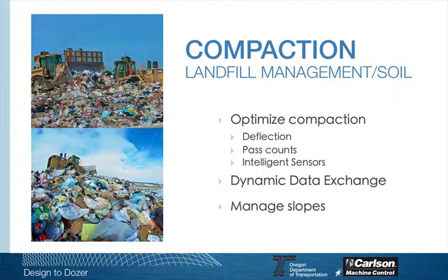The other thing that they require that machine control contributes to is managing slopes. Even in a landfill where it's trash, we need to make sure that the slopes are managed correctly and that the slopes don't fail and that the machines are not working against too steep a slope, etc. So the technology lets us know how to build a 2-to-1 slope, for example.